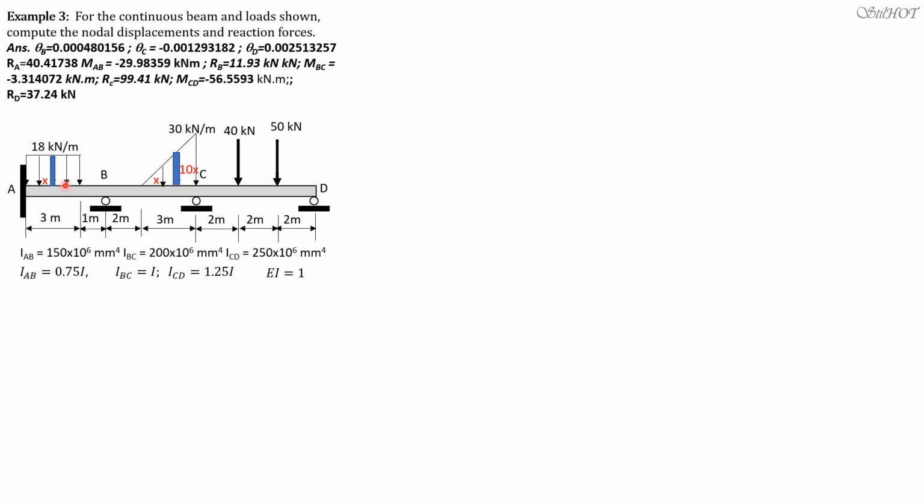So we're now ready to set up the moment equation for A to B. Moment AB, A is our near end, is equal to 2 times EI, which is 0.75, over 4, the span, times 2 theta A, which is 0, plus theta B, then minus 3 times delta over L, because A and B are supports that do not settle, so 0.